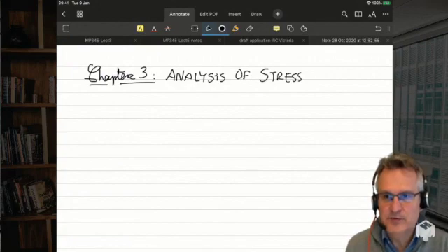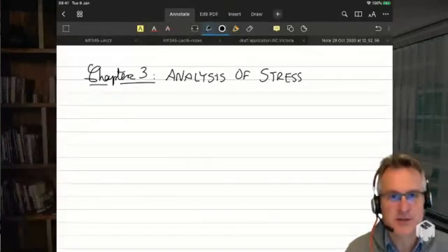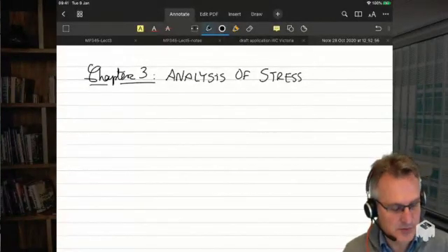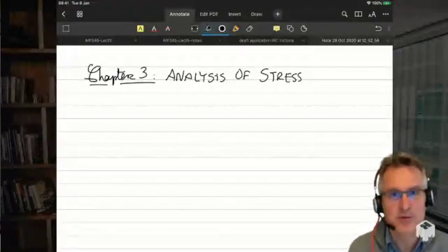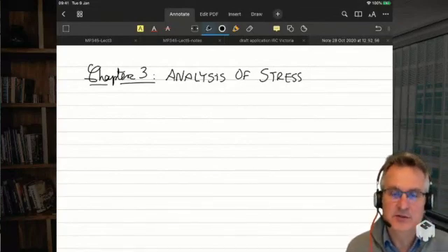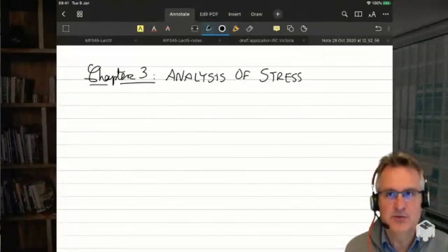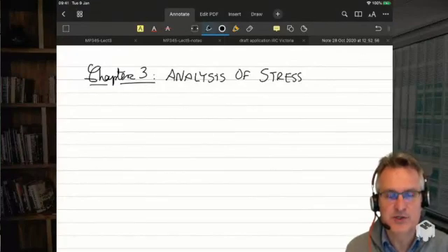So far, we've seen how to describe deformation, right? And we introduced this very important object, the deformation gradient. And from this, we could see that locally we could gain a lot of information about how angles deform, or lengths, or volumes, areas, and so on. If the deformation is homogeneous, the deformation gradient is constant, and so whatever you find locally is what happens everywhere.